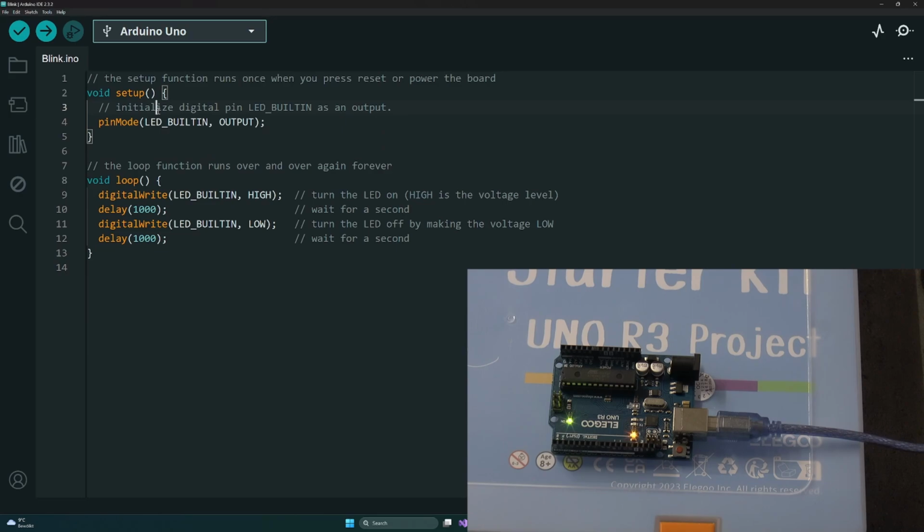So it's really important that you know your microcontroller, or in case of Arduino, just tell the pin mode for every pin that you are using so that Arduino can properly initialize that. On a microcontroller, it's a bit different. For example, I know that the AVR by default treats all pins as an input. So if I have a default input and I don't want to change something, I don't need to specify the pin mode. But it's a different story when we are talking about the Arduino.